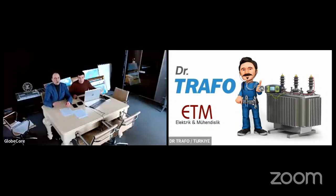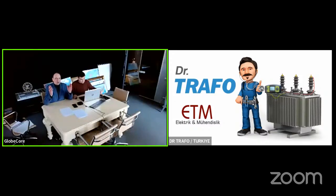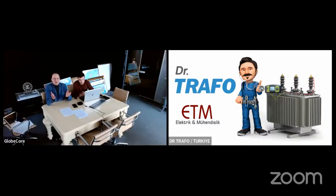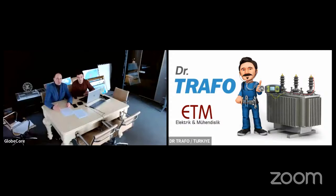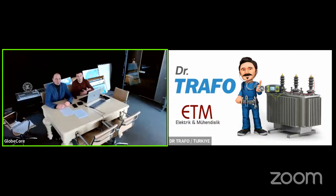But as I told you, there are a lot of different factors. It can also be the quality of the transformer, if the transformer is hermetically sealed or not, if there is any leakage of air in the transformer, so we cannot tell you a number of years which can be enough between the regenerations, because it's impossible to say. But we can provide you the instructions how to make the regeneration properly, to prolong the lifetime of the transformer, and to make it correctly in the proper manner.